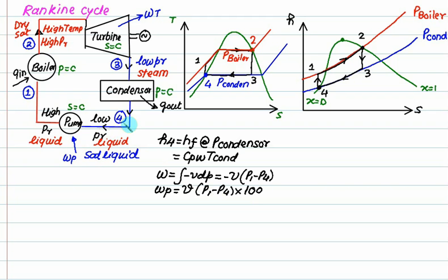So this quantity is H4. If you draw this diagram like this, initially you are present with enthalpy equal to what? H4. You are giving the WP, and finally you are available with H1. So does it mean that H1 equals H4 plus WP, by first law, conservation of energy, energy in equals energy out.